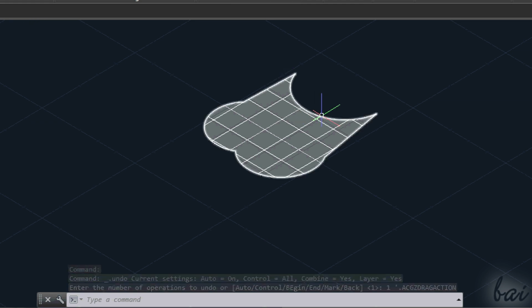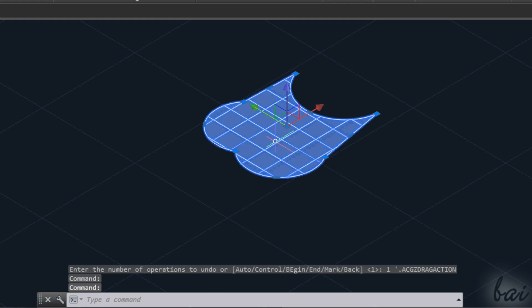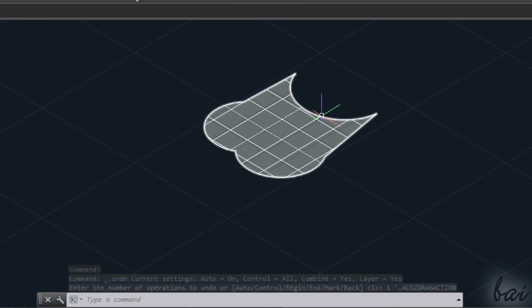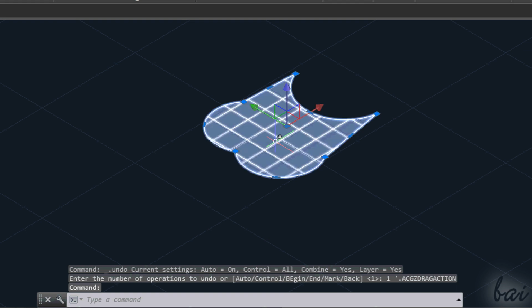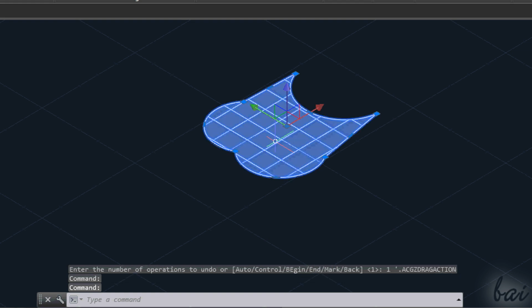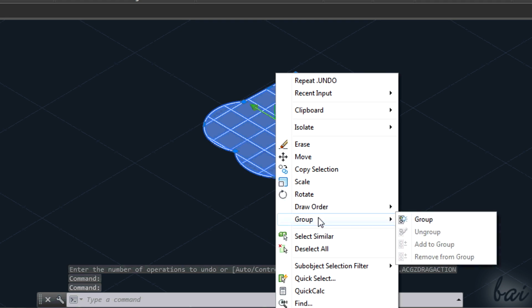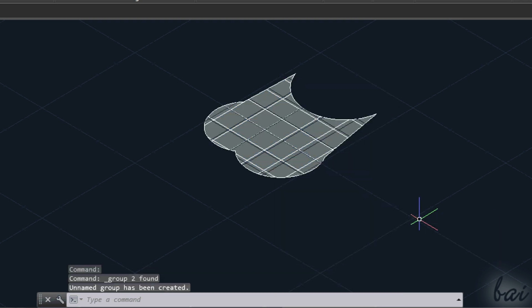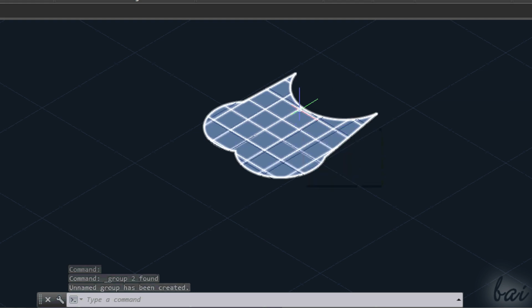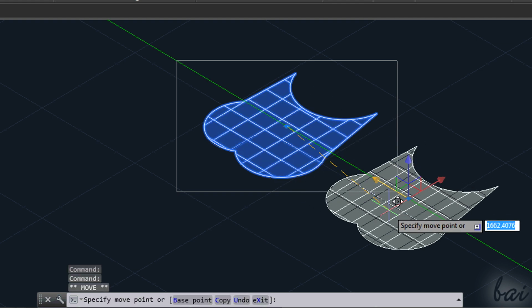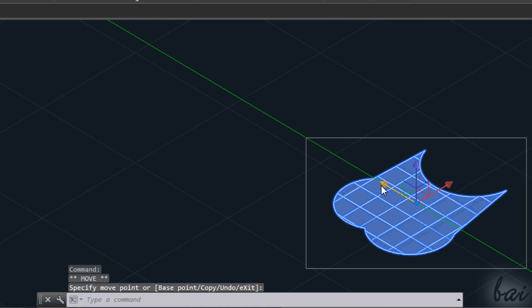all in one piece. This is how any surface is represented. Keep in mind that it's better that the contour and the surface always go together, since some commands do work with such contour and not with the surface itself. To group all of them, simply select them all, right-click and go to Group. In this way you will treat contour and surface always in the same way. If you want to know more about groups, watch the related video in this show.